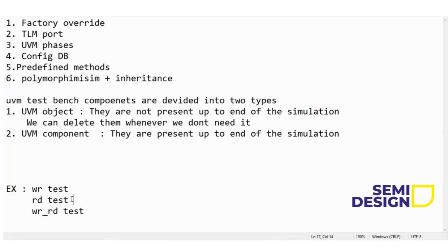Yes. Okay. So now the question is, can I delete the driver? No, because for the write test, once the work is done, I don't need the transactor class related to the write test. But I still need the driver, because I cannot say that for the write test I need one driver and for the read test a different driver.